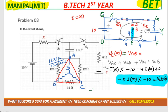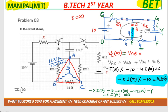I'm putting down the equation: minus x I of infinity minus 10 minus 4 I of infinity minus 4, ये वाला 4, I of infinity minus y, and then this one is 6 ohm, so minus 6 I of infinity is equal to 0. Here you will substitute the values of x and y, and you will get the value of I of infinity from here, and putting the value of I of infinity over here, you will get VC of infinity. Okay, note it down.